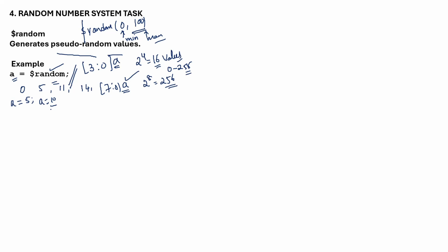No problem, but it is passing only manually. If you check with random values, they will ask you to give some random test cases, because UVM automatically randomizes the variables.